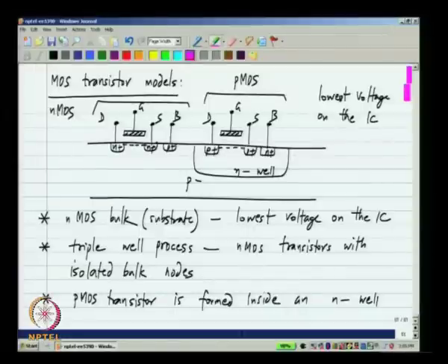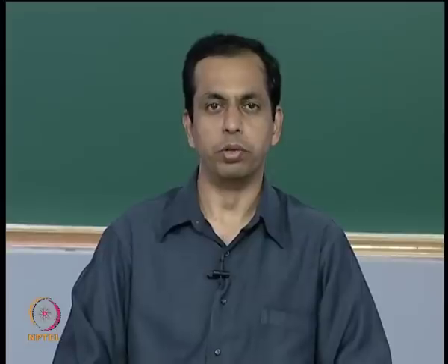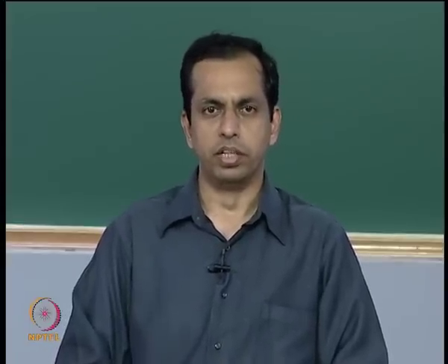In discrete component circuits, every component is separate. Okay. If you have two transistors, they will be in separate packages and there really is no communication between them, so to speak. Whereas, on an integrated circuit, if you have 100 transistors, they all share a common substrate. So, they will in some way talk to each other, there is something common to them. Now, in order to isolate them, we need to take care of some things.